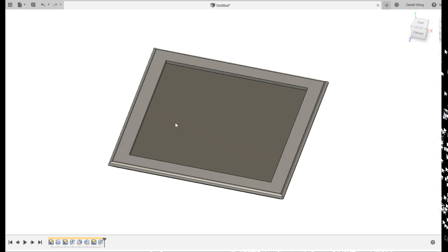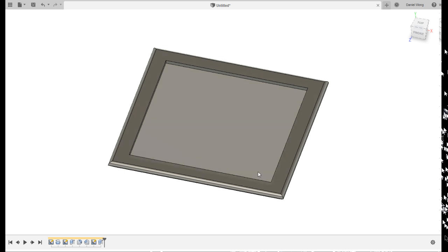Because the recess is happening over a path, we're going to use the sweep function. So you can imagine that if I can build a cutting profile along this rail, I can make it sweep across the rail and cut this dynamic shape along the entire rail, which is going to be pretty cool, right?